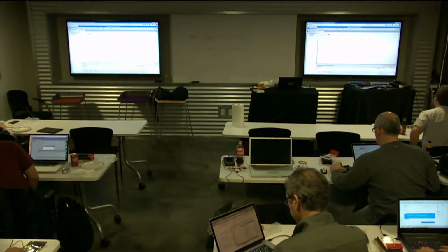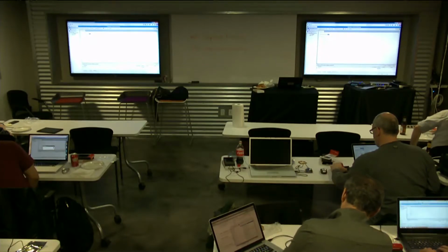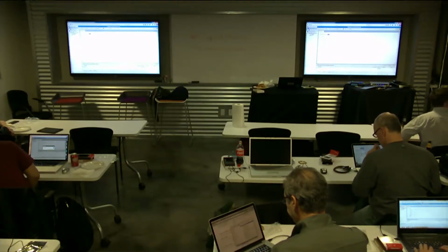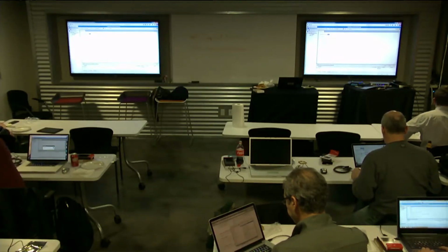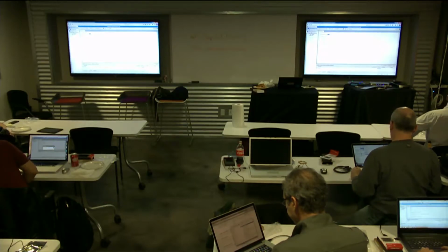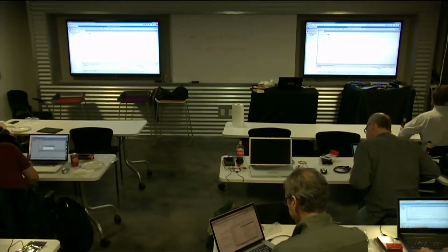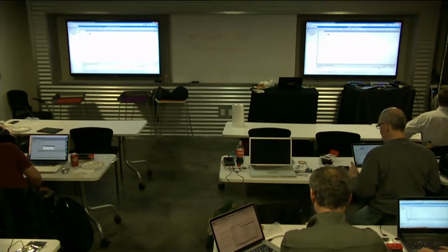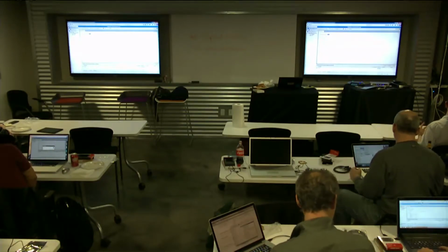I just downloaded this, but I could just as easily not have that type of code. Just say 1 equals 0, turn it on. Exactly. Keep in mind though, this LED Freescale for some reason puts a negative logic LED on there. So 0 is on, 1 is off. It's just a little thing they did because it was cheaper.